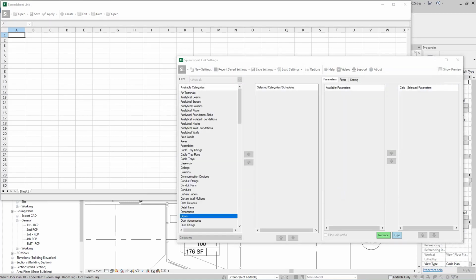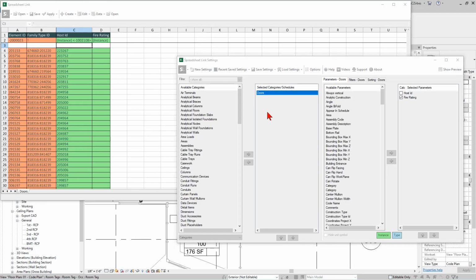Open this up. It's going to take it a second because it's going to have to scan all my doors, scan all my walls, get their properties, pull them into the list, write the formula and populate it. But once it populates that formula, all of my doors inside of here are going to automatically populate with the properties from the walls. It really takes, what, 10, 15 seconds here for these to all fully load and populate, and then I can simply apply the active worksheet back, and I don't have to know all of the individual formulas and functions that I really want this to use.